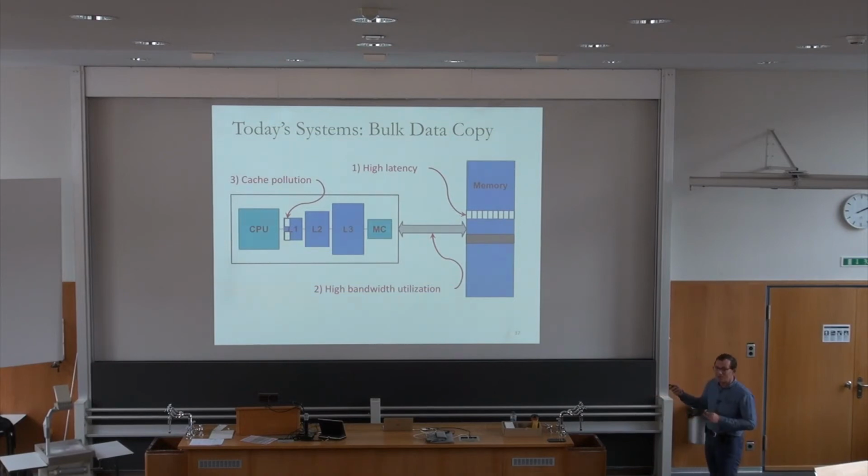But you could eliminate that today actually by doing this operation through the direct memory access engine. All of the chips that I know of provide access to a direct memory access engine, where you could just do the copying through the memory controller. You need to set up and tear down that direct memory access, of course, which takes some time. But okay, you could eliminate the cache pollution today. And this caused a lot of unwanted data movement.